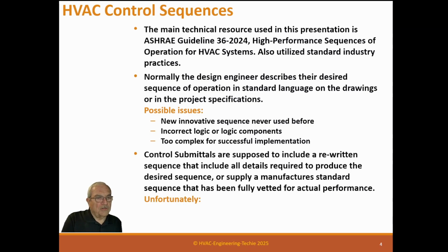Normally, control submittals are supposed to include a rewritten sequence that includes all details required to produce the desired sequence, or supply a manufacturer standard sequence that has been fully vetted for actual performance. Unfortunately, that's not the way it actually happens. That's how it's supposed to happen. Because you realize that the engineer writes a sequence in English, but programmers don't program in English. They program in the syntax of the language they're programming in, which is a lot different. So there's a lot of information that a programmer actually has to put into a program beyond that English language description of what the engineer wants it to do.